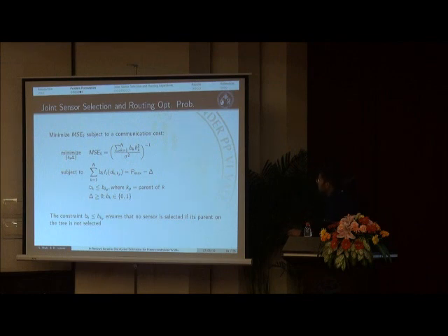This set, I mean the set of sensor k and its parent, is obtained from the Bellman-Ford algorithm. That has to be stored. So this ensures that the routing, since we are going to select only a subset of sensors, generates a tree T that has to be rooted at the sink node, because we are going to pick sensor k only if its parent is picked. So this forces that subset selection to be rooted at the sink node, so that we can get the total estimation as well as routing.